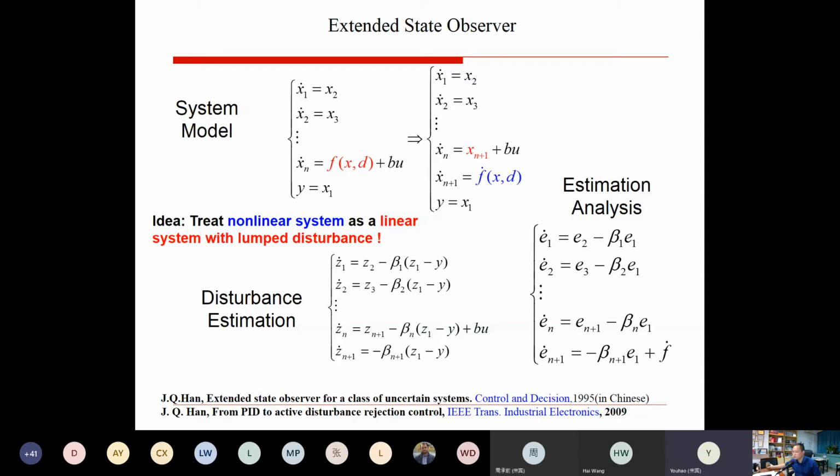Yes, right. If you model x with the power of 3, then sometimes if you assume the modeling error is bounded, maybe it's acceptable. Even taking the modeling error plus the external disturbance as a lumped disturbance, maybe it's acceptable, because most of the time you have accurate cancellation of the nonlinearity.